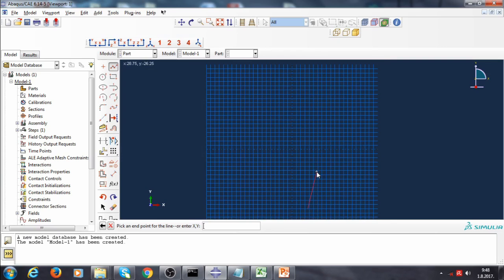Oh, it's here, we can see it. Now the next coordinate is 70, minus 70. Basically these coordinates represent the edges of the cross section. Click enter again. So 70, minus 80, 0, minus 80, 0, 80, 70, 80, 70, 70, 18.5, 70. Click enter and click escape now.